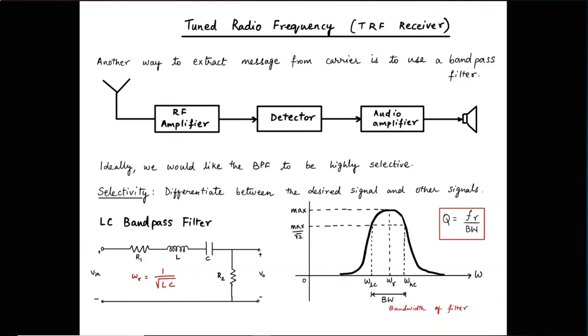So what we have here is a sound application. We get the received signal using the receive antenna. We amplify the RF signal first, go through a detector which has a bandpass filter to extract the signal, and then we will also have to follow the bandpass filter up with another demodulation. So we may use an asynchronous demodulation after that. And then we have an audio amplifier which drives the speaker.